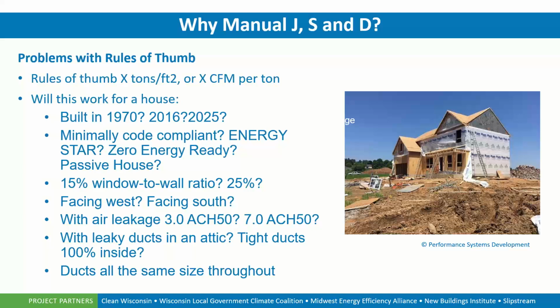I think what I mentioned also about, because we always did it this way, we're throwing a 7-inch line to every room. Well, that may or may not work based on the airflow and the distance for that line to run, the amount of turns and so forth. So all of that needs to be calculated in, which comes down to the terminology of friction loss. So the longer the pipe, the more bends and turns, and the diameter all affect how the air flows through, at what speed and volume it gets to its final destination. So that all relates to what's known as the friction rate of that ductwork.